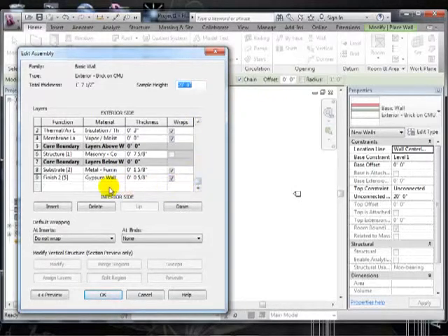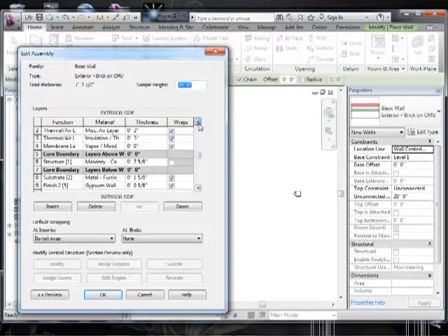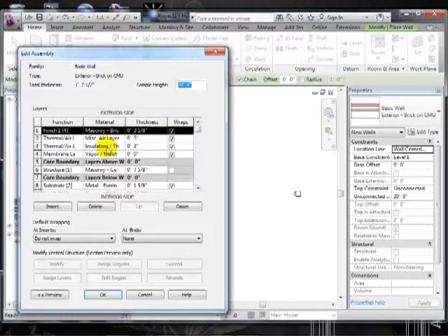In this case, it looks like it's about 5/8 inch of sheetrock with some metal furring behind it. Then that's on top of the masonry, the CMU wall, 8 inches thick or 7 5/8 in actual dimensions. They're showing a moisture barrier, 3 inches of some sort of insulation, probably rigid foam insulation. Then an air barrier, and finally the brick on the outside. That may map to your wall, or it may not be like your wall, and if you need to change that, you can.